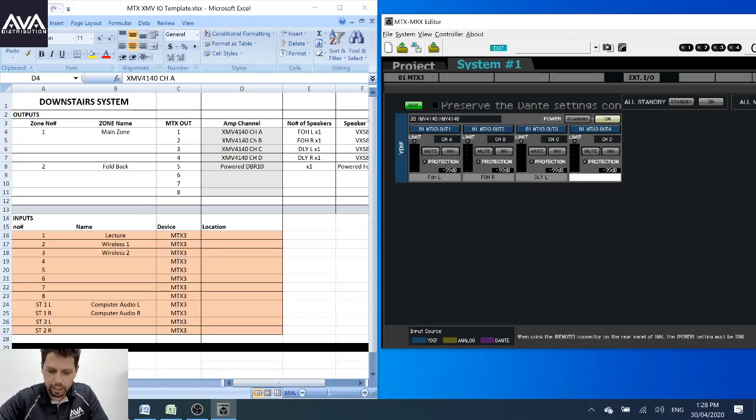Delay left and delay right. So a good starting point, I always like to start at -20 attenuation. That lets 80% of the sound through. It's a good way to never let your system peak, and so when the end user drives the system to full capacity based on what you've given them in the programming, you'll know that that signal, when it passes through, won't peak the amps. But ideally, if you want 100% of the signal to flow through, we want all our amps at 0 dB.